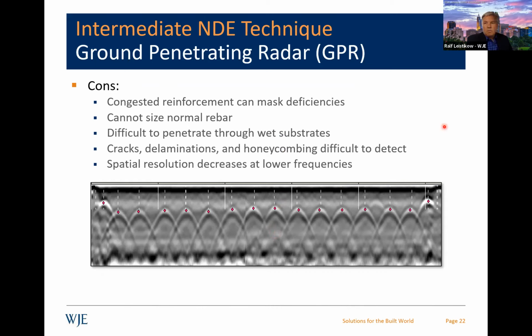You also can tell the rebar size, and as Jason kind of alluded to, we always verify. So part of the work would certainly involve doing some openings or drilling some holes to verify maybe the rebar sizes. So that's kind of important. The other thing that can happen is, it is difficult to work with this equipment if it's wet, and it actually does impact some of your readings as well.